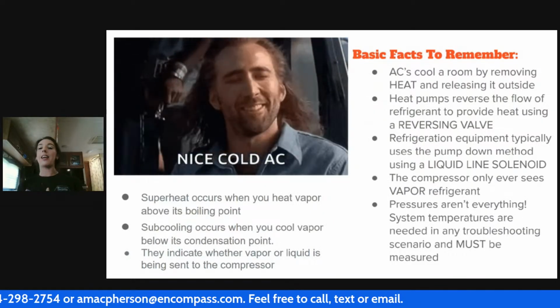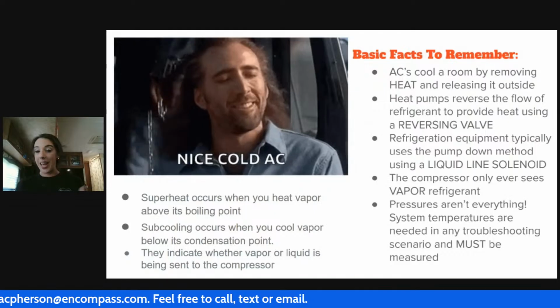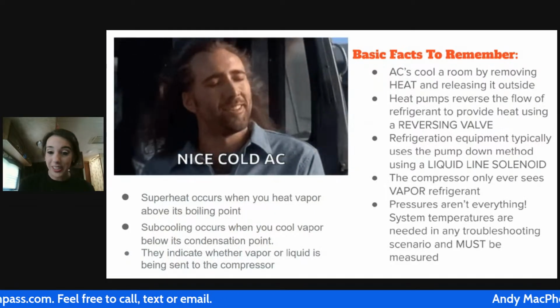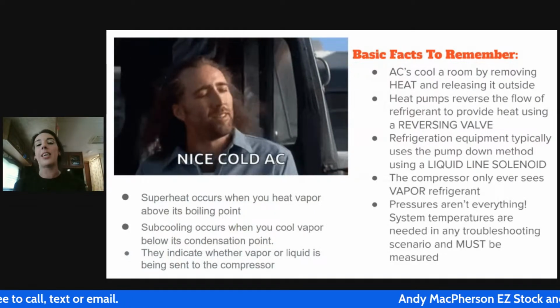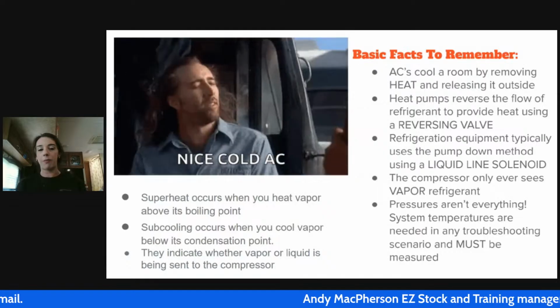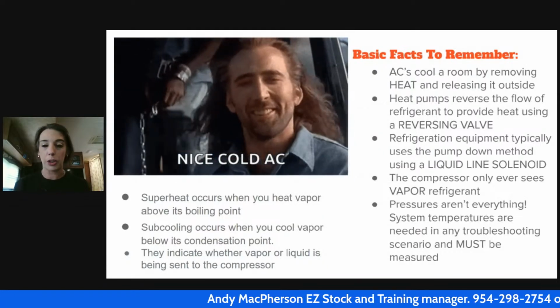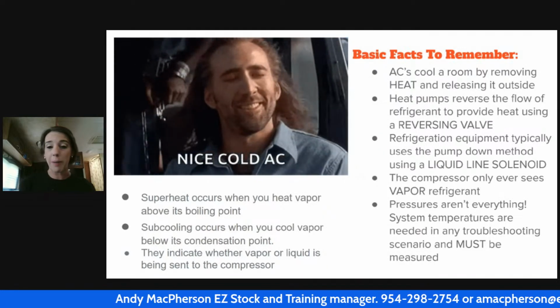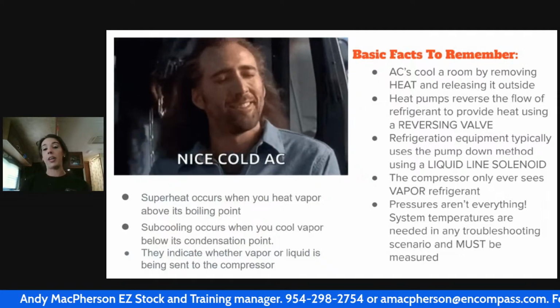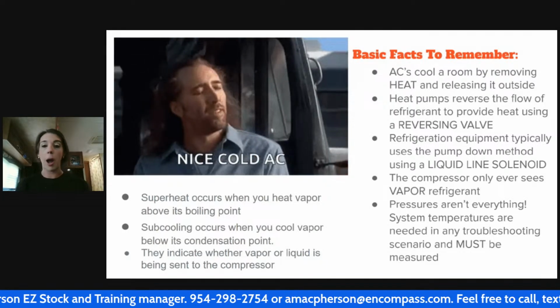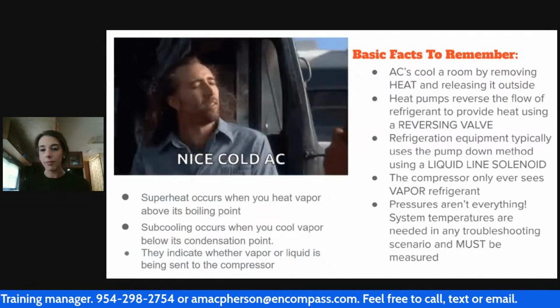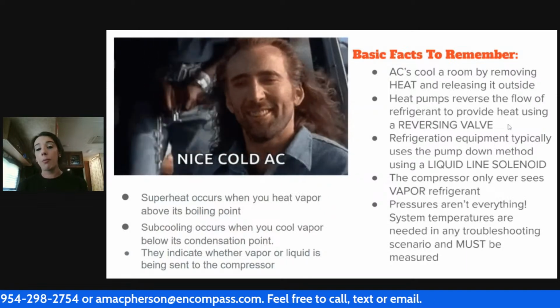We condition it again past the coil. And then now we might have 65-degree air. And we keep doing that until we have the best possible temperature of treated air, and we reach set point. So this is the perfect solution to the problem of heat in your home. But again, we don't blow cold air in, we remove heat.